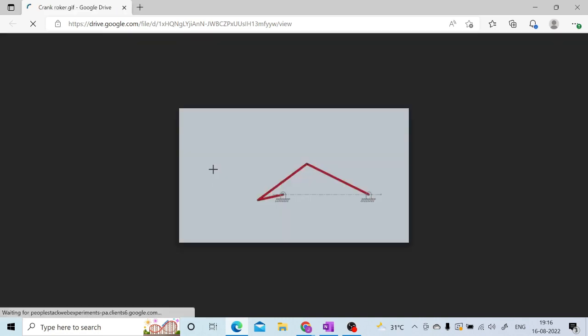So you can see this is crank and rocker mechanism, in which you are having the smallest link having full revolution, and that output link is having oscillatory motion. Output link is known as rocker, while the link having full rotation is known as crank. So when you fix the link adjacent to crank, you will have this kind of crank and rocker mechanism, right? Similarly, you can see this is used in your beam engine actually. Beam engine is one of the inversions of the 4-bar chain mechanism.